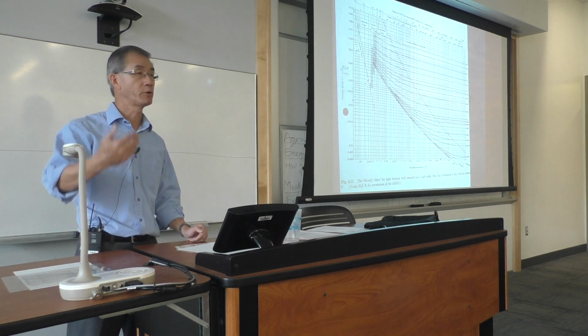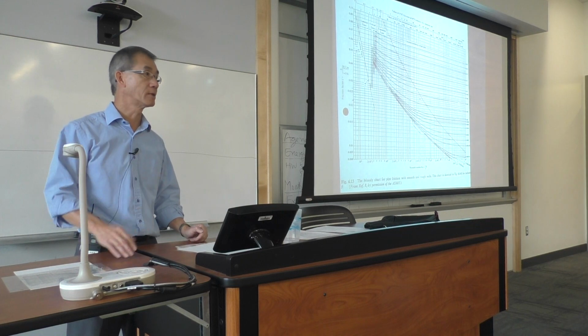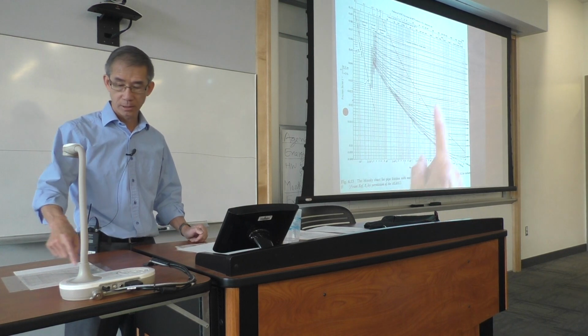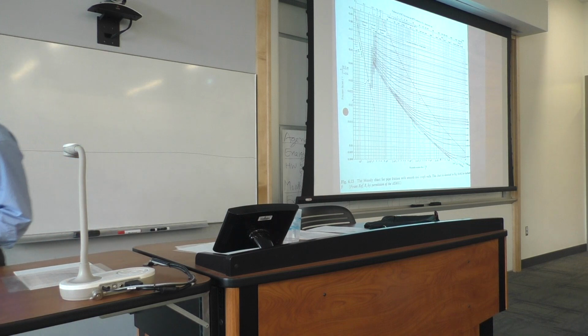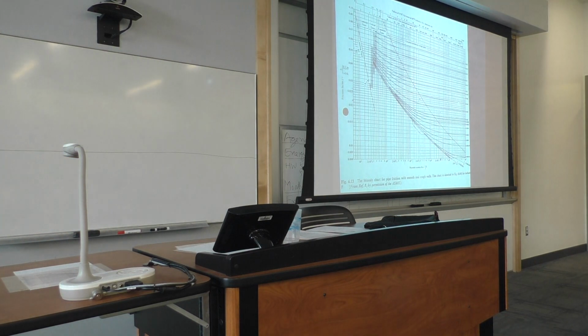So we obtain an average friction factor for that set of data. That friction factor is used to create the y-axis. So if you're Mr. Moody, you have done the experiment, either in air, in water, or in oil, and this is how you get the friction factor. You measure the pressure loss, and then you use the formula we define for the friction factor, and you calculate that, and that gets your data point at a specific Reynolds number, 1 point.